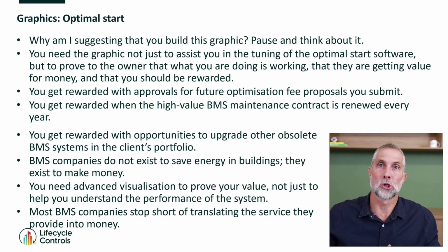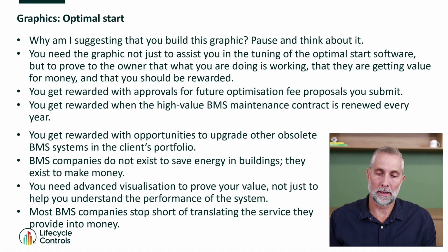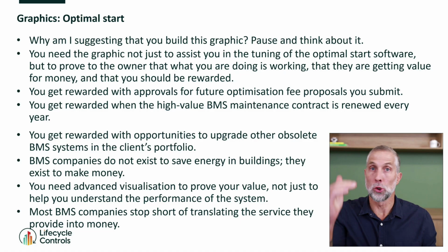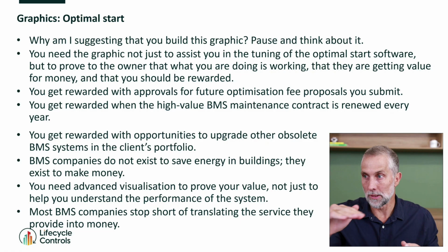Or if I say to you, how's this? Warning, off-topic discussion approaching. You know that an air handling unit's supply air temperature set point reset and its supply air pressure reset strategy are actually related to each other. If you drop the AHU supply air temperature set point, say 2 degrees, the cooling valve opens and the temperature drops 2 degrees.